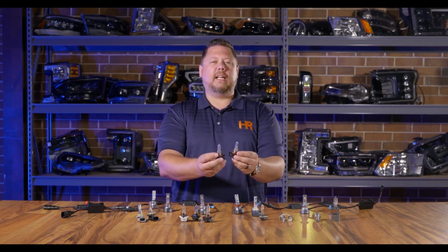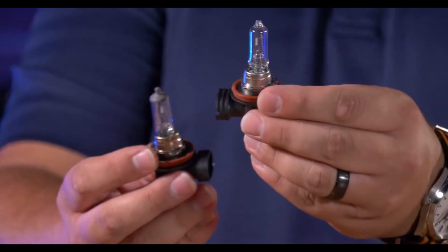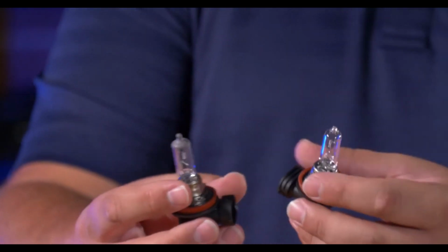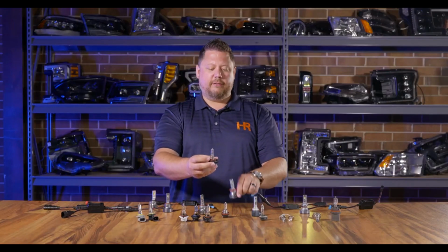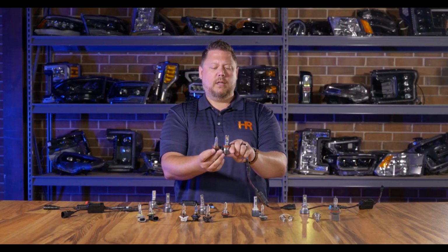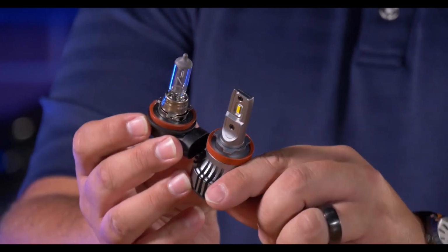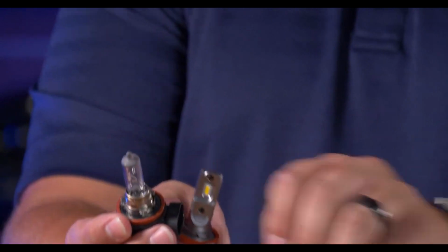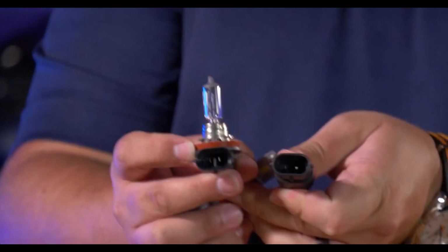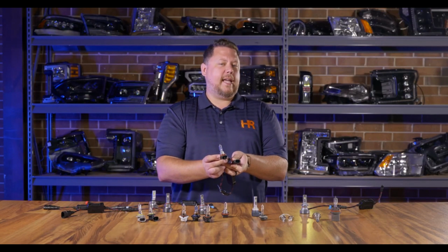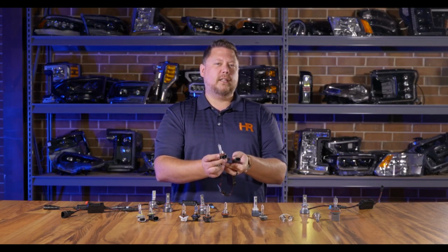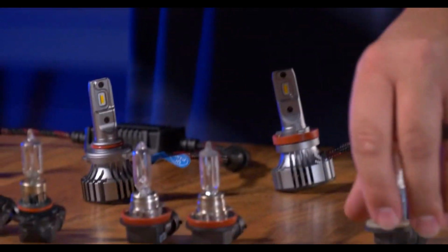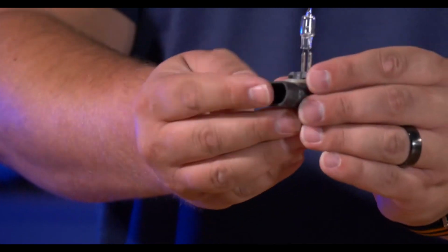So instead of these LED bulb manufacturers making an H8, H9, and H11, they make one bulb that fits them all. You can see here's the H11 version with the same O-ring, the same mounting tabs. The LED chip is in the same place as your filament, and the wire harness is the same. So if you have an H8 light bulb in your fog lights, but all you can find is an H11, that's the right bulb.